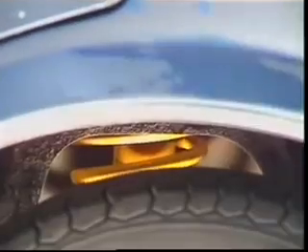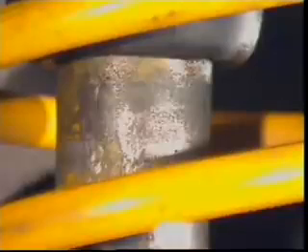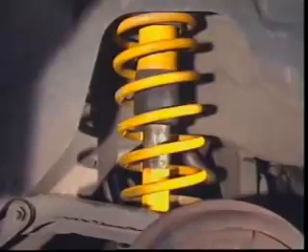But when a heavy load is placed on the rear of the vehicle, the rubber air cylinder can be pressurized to assist the suspension springs. By changing the air pressure in the cylinder, the ride height can be adjusted, as well as the stiffness of the suspension. Compressed air in the pneumatic cylinder can absorb smaller road shocks and provide better ride characteristics than just stiff springs alone.